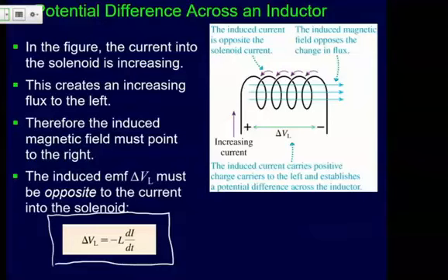And if you look at how that current would be going, that current is going in a direction that opposes this current. In a sense, you're creating something that's going to send current that way. And so this would be our positive end, and this would be our negative end. So here, increasing current, you see the sign from this equation: if the current change is positive, then this is a negative. So as your current goes through here, the voltage drops. So we have the same positive and negatives that we would have used for resistors.